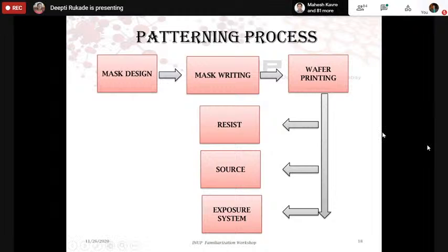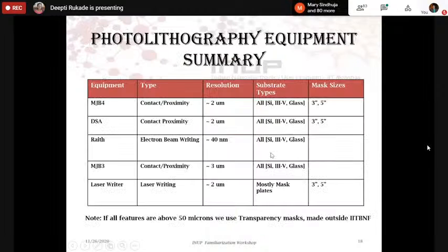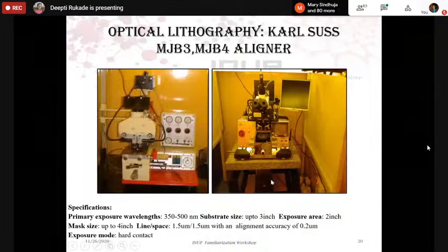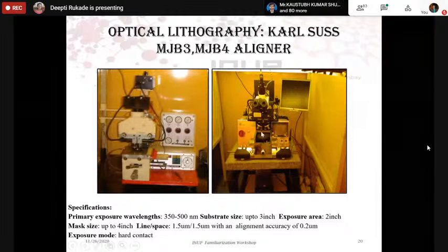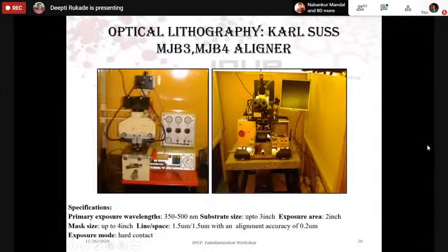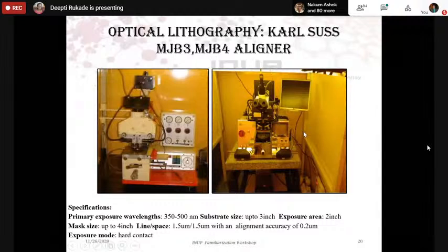So how do you do that is in these steps. You put it with the resist, expose it to the source, and then you develop it, which was there in the lift off thing. So how do you do this process? I will just show by images. Can you see this image which is to your right hand side? Yes, ma'am. So there you see a circle here where the cursor is pointing. Yes, it is in gray color. Yes, right, exactly. So you have something that is called a hard mask.